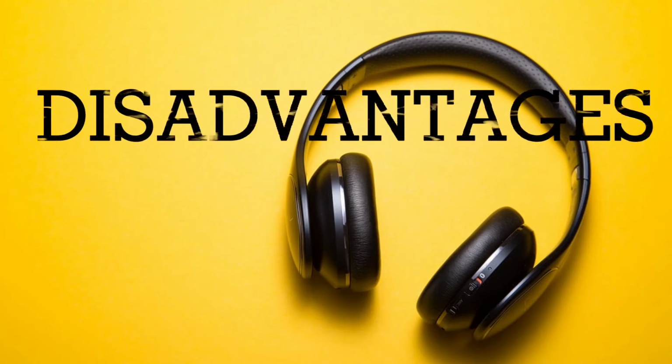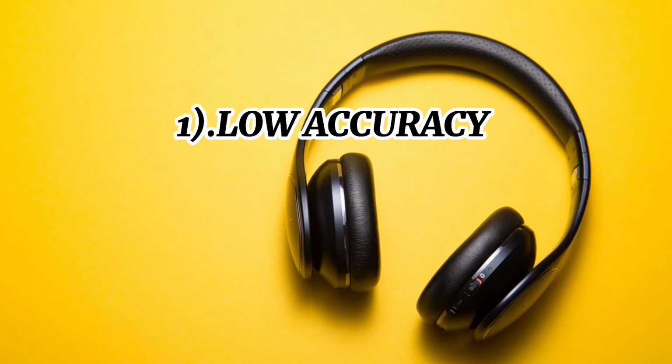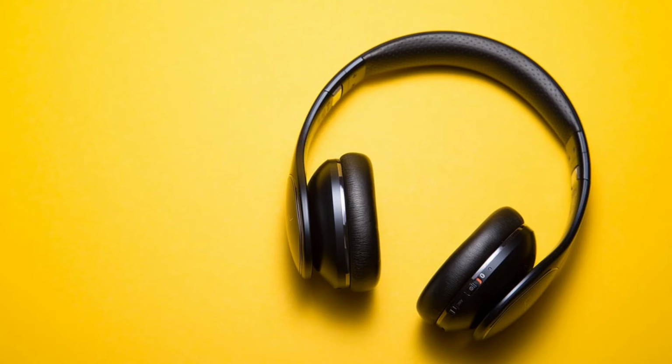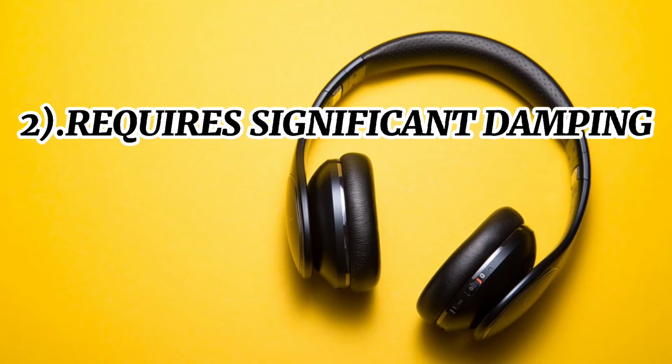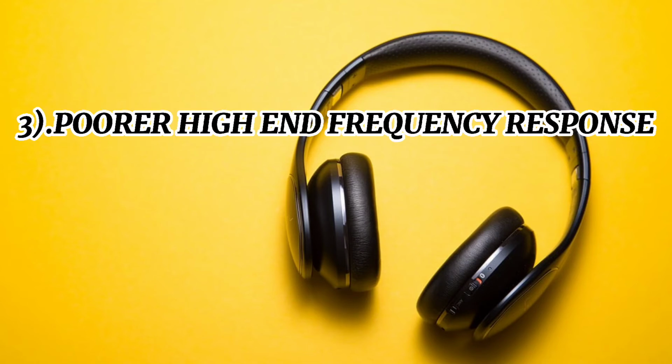But there are some disadvantages as well. Accuracy can be low in transient response because of diaphragm inertia and mass. Also, headphones require significant damping and tuning due to resonance frequencies. Poorer high-end frequency response. Relatively, the large coil and thick diaphragm may have more difficulty than other driver types when producing the short wavelength vibrations required to make high-frequency sound waves.